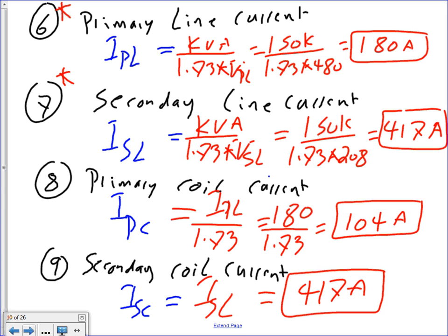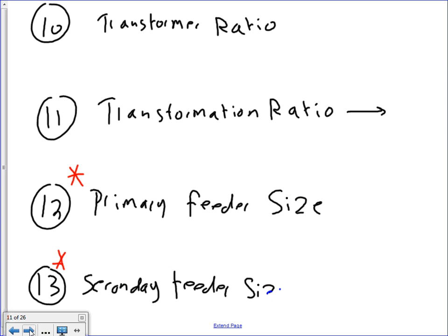In your homework number 1, it says 100 kVA per transformer. That's supposed to be per phase. Per transformer, it is actually; every transformer is a phase. If you have 3 single phase transformers, every transformer makes a phase. So long story short, you multiply them by 3. Should we go to 10? Anybody? Yes? No, Darren? Yes, Aaron? He was talking about the homework. The homework is 100 each.